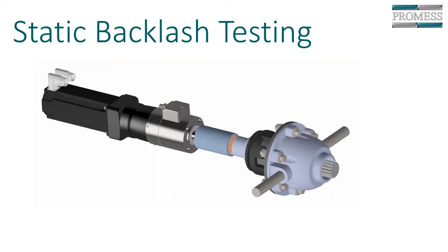And for each point, the torque unit will actually apply a torque in one direction. Well, I should back up. On the output shaft, we're actually breaking that and making that rigid. And at each point, along these 8 points, we're actually moving the torque unit forward to a known torque and then backward to a known torque.